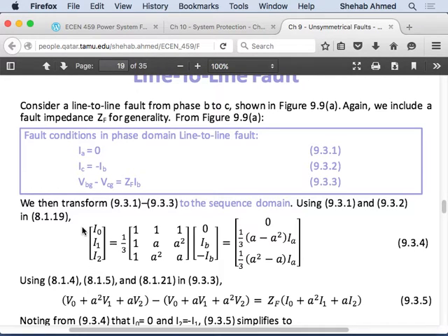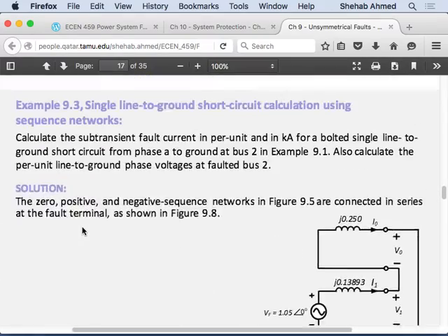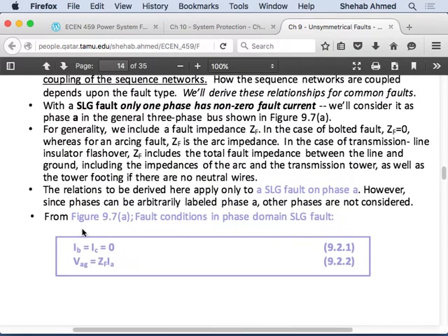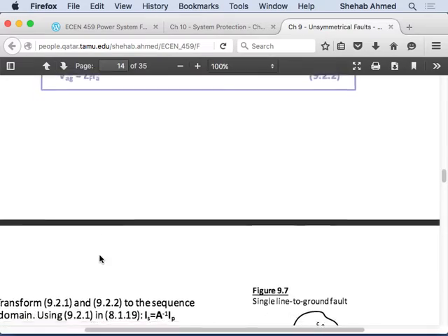For the previous single line to ground, we assumed that IB and IC are 0. We had the fault on phase A, but it doesn't matter. If you assume that the fault was on phase B, you have to assume IA and IC are 0, and you rewrite these equations, right? But then in the matrices, when we...